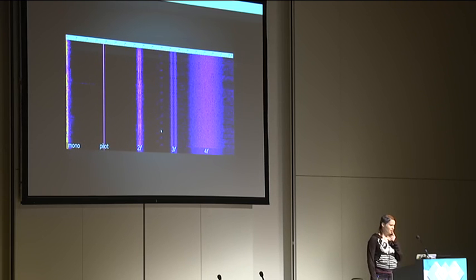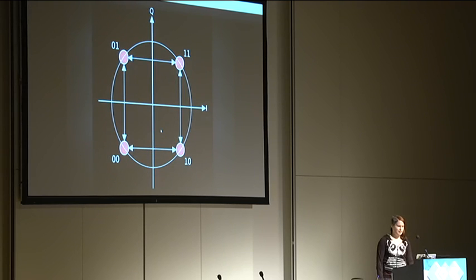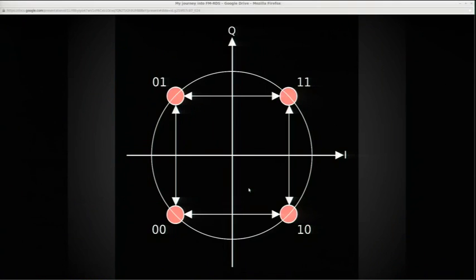So I started by Googling for 76 kilohertz, and I found something called DARC, or Data Radio Channel. It's not to be confused with RDS, which is Radio Data System, of course. These are very imaginative names. And I found out it's a much more complex modulation scheme. It uses QPSK, which is a 4-phase modulation scheme.